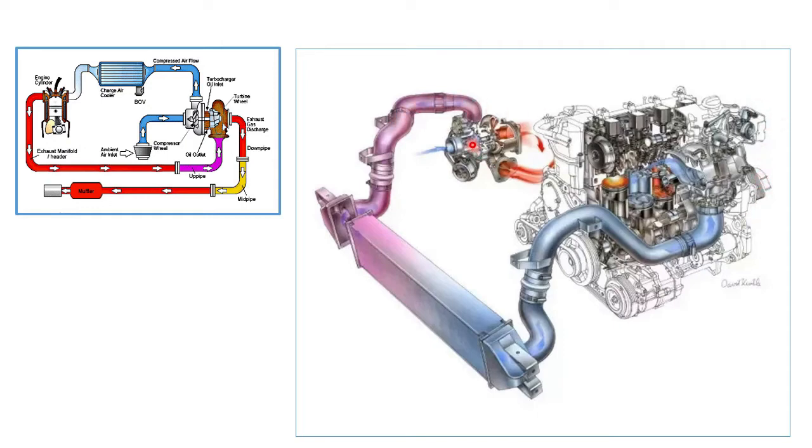You can see right from the turbocharger, these pipes, these are the hoses, these are the steel pipes, again these are the rubber hoses, these are the clamps, this is the intercooler or charge air cooler. Again you can see hoses, clamps, so many things. This is one hose which looks like this. When you observe this particular design, it has a lot of bends and a lot of pipes, which is not desirable.